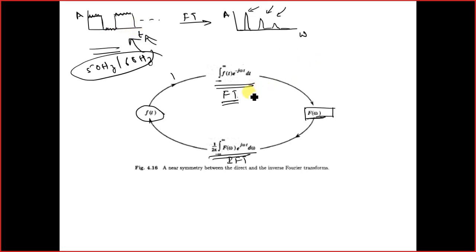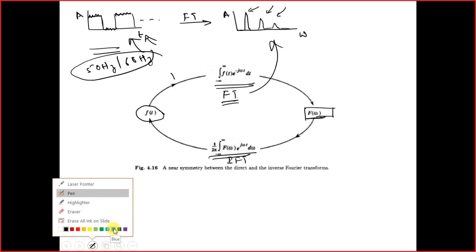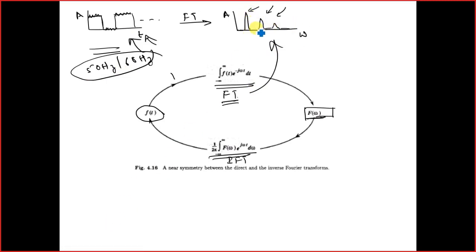Here, the Fourier transform helps us. If we have any power line interference, in addition to the frequency components we have discussed, we may be getting a peak around that frequency component. From there we will have an understanding about the nature of the noise. Once you know the nature of the noise, you can design your filters efficiently.